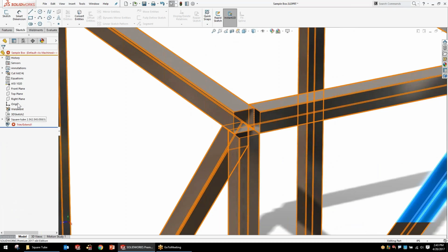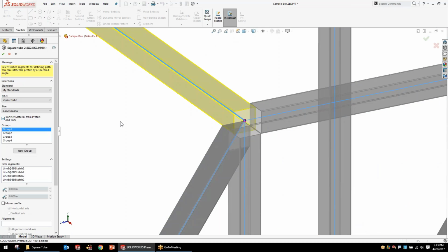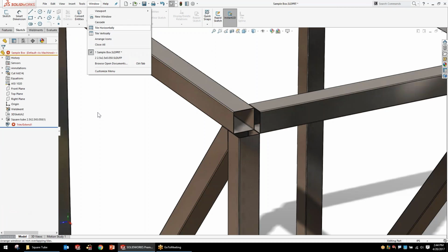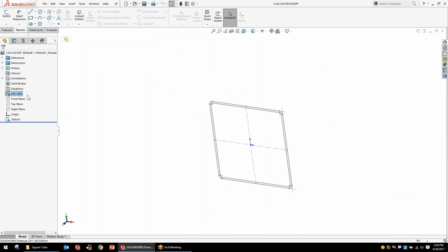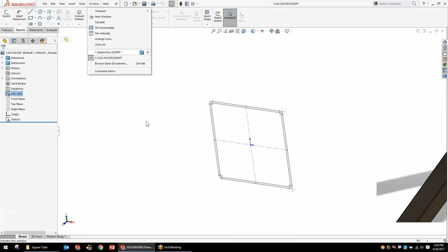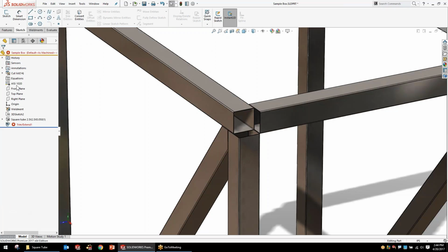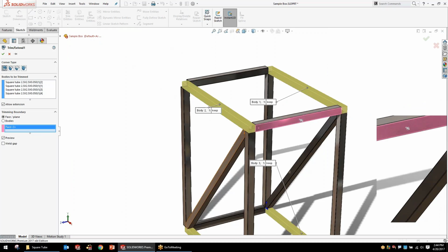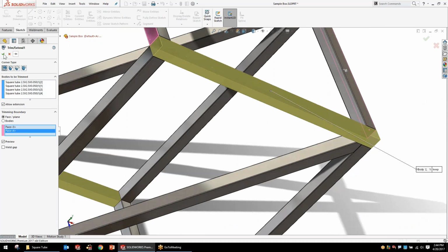One thing that is nifty with SOLIDWORKS that they added in 2016 is you have the ability to transfer over material. So I had a material applied to our profile. Here I had it set that this was 1020 steel, and because of that, when I saved it out, I was able to auto apply the material for this part to be 1020 steel. Now, because of our slight change, we do need to update this trim extend feature to the new faces created by the new features.